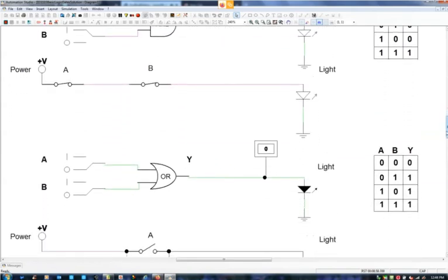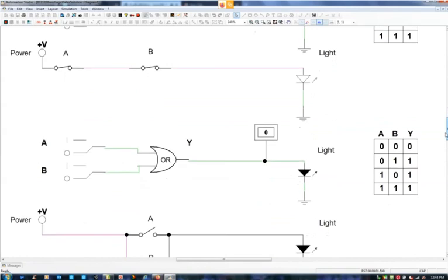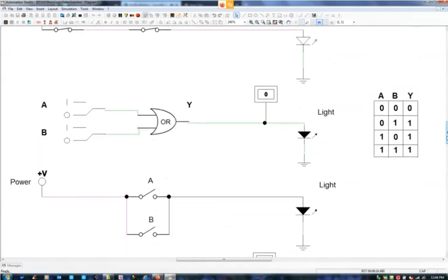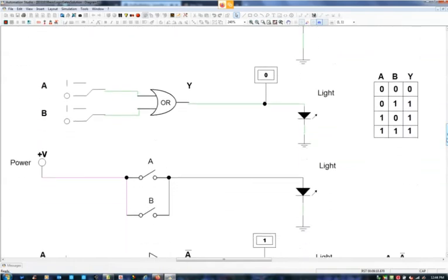The other instruction is called an OR. Looking at the truth table here, you can see that an OR instruction has, in this case, 2 inputs. OR has the same amount of combinations, but I can scroll up a little more here just to get the switches. It's like 2 switches in parallel. So think of start buttons.